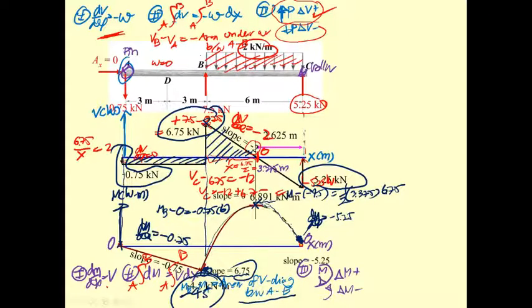So this is going to be the result of the moment diagram. Also, this is an important one: this is the point of zero moment, and the curve will change. This is positive, so it is upward concave; this is downward concave. So the elastic curve, since this is a pin and this is a roller, this is downward and this is upward.